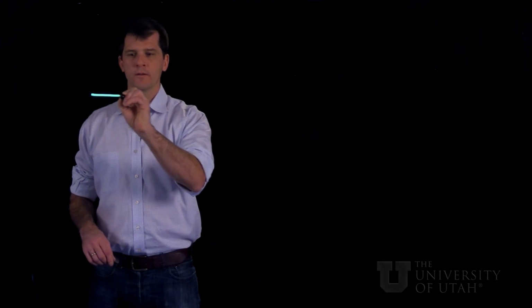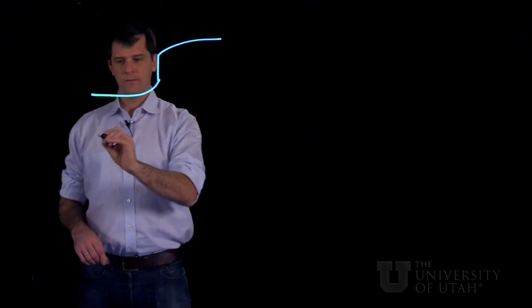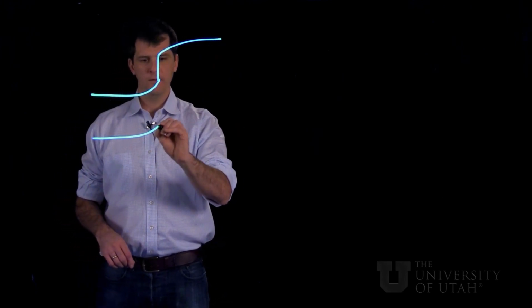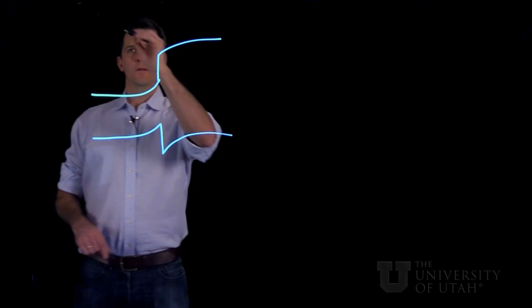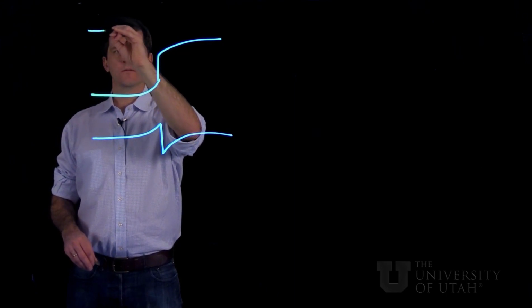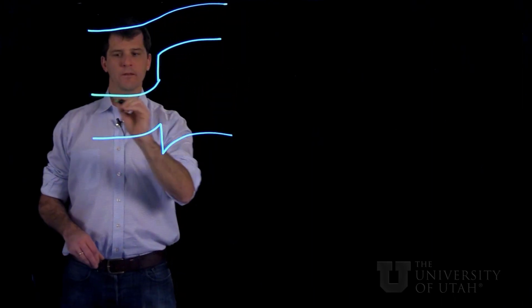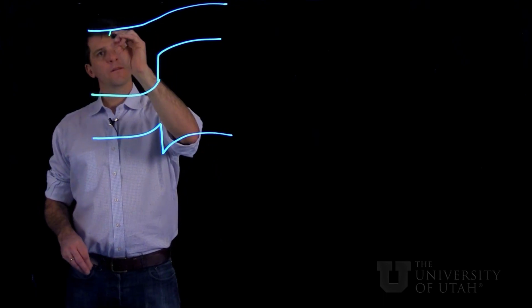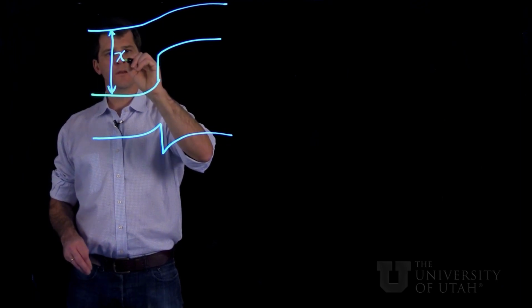So first, a word about what happens to the vacuum level. When we introduce the band bending in this N capital P junction that we were just talking about, what actually needs to happen is that the vacuum potential bends like this. And this is a consequence of assuming that our electron affinities remain the same.